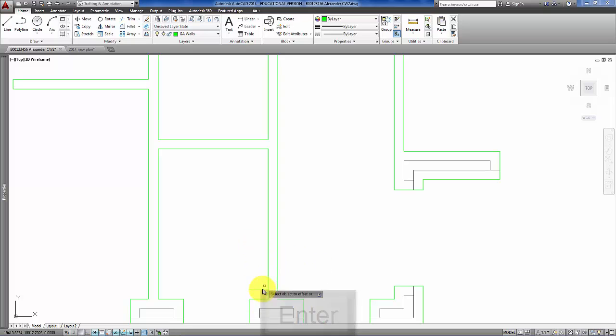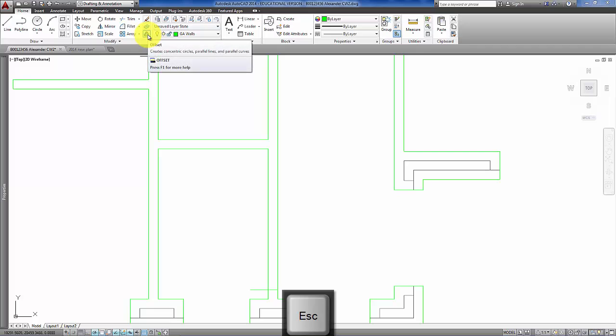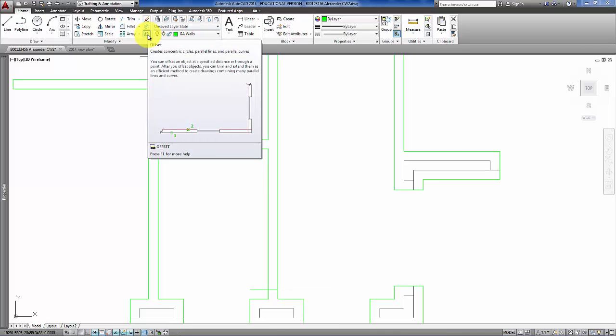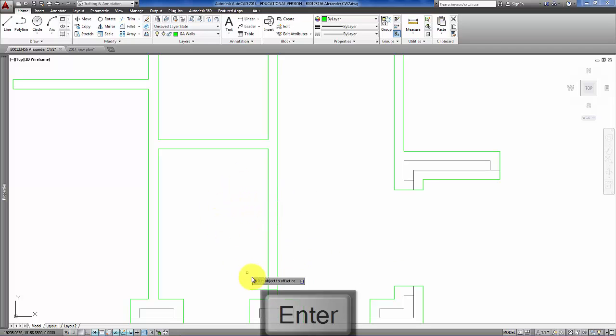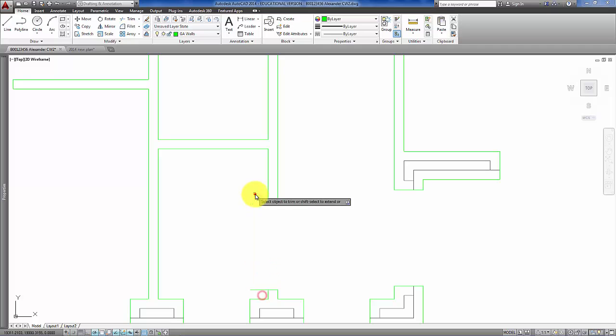The reason for doing that is it's just good practice to keep the door out from an adjacent wall, so that the handle doesn't damage a wall or something behind there when it's opened. And offset a distance of 910 for all of these internal doors. And then we can use the trim tool to trim out those lines.